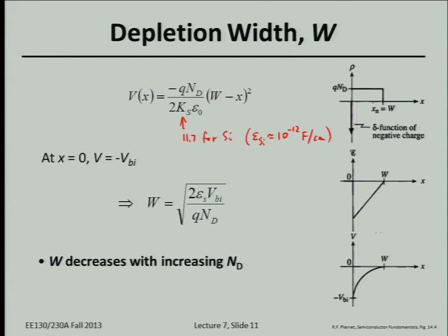Okay? And the reason for that is because of the area. Just to show graphically, what does this area represent? Yeah, the area is the total voltage drop across the silicon, right? So if you want to drop more voltage, let's say the difference in work function was greater, that means you have to have more built-in potential to equilibrate the currents flowing to the left and right. If you have a larger difference in work function, you have a larger built-in potential that you need to build up to counteract diffusion. That means you need a larger area underneath this E versus X curve.